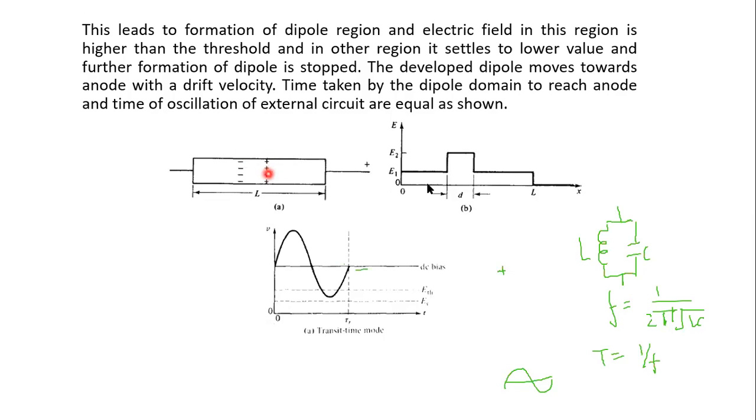Okay. Now you can treat this entire thing as a pulse. You have created a pulse. This pulse is nothing but this bunch of electrons which is moving towards the cathode. And on the other hand, you are having this circuitry. If this pulse is given to a tuned circuitry, which is oscillating at this frequency f, okay, it is tuned to this frequency, suppose, the moment this pulse drops here, the oscillation will start.